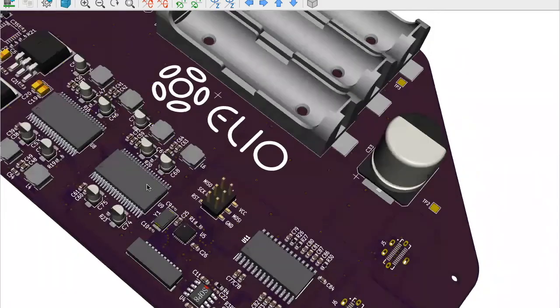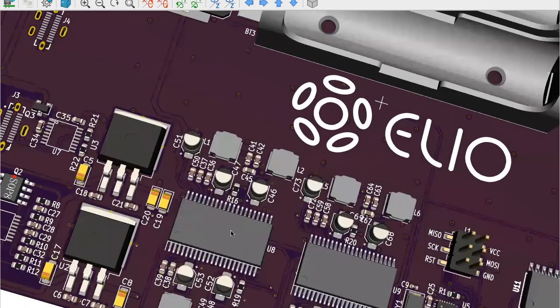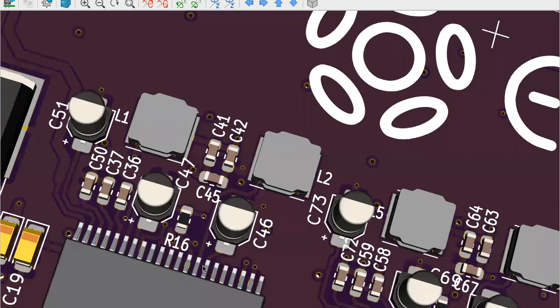So when you come to solder these particular edges, solder mask is what flows in between here, here, and here, such that when you are soldering this, it doesn't overflow to this one and cause a short and stuff like this.